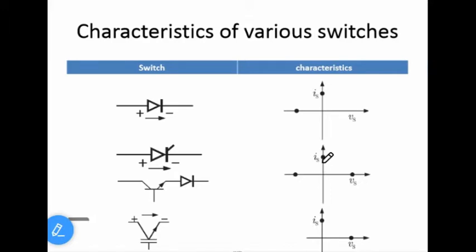And this current depends upon the load. We will be getting the operating characteristics on the positive y-axis at different points. And since the switch is in on condition, since we considered an ideal switch, the voltage across the switch is 0.